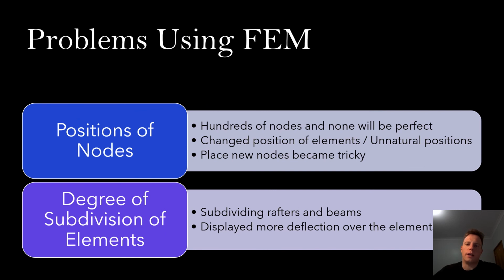Some problems in the modelling included the incorrect positions of nodes in the model. These nodes were deleted, and through measuring similar positioned elements, an estimate was used to determine the length and position of some of the nodes throughout the model. Another small hiccup occurred when deciding the degree of subdivision used for splitting elements to better display forces affecting the structure. Although the deflections were clear, a higher degree of subdivision could have made it clearer.